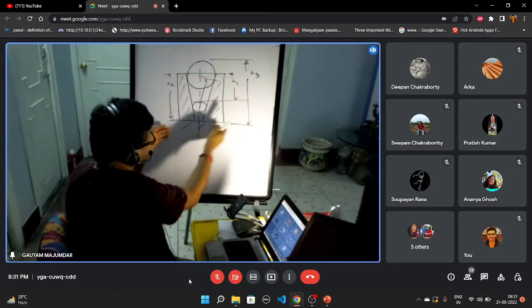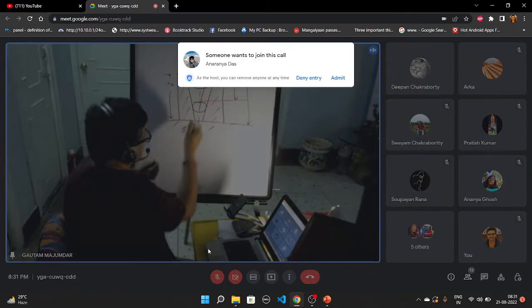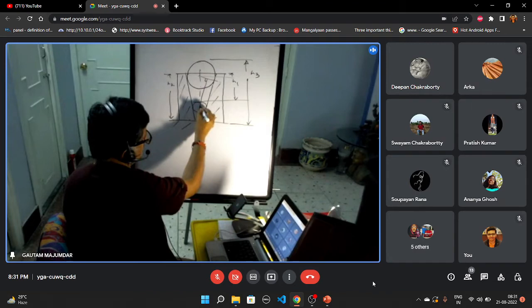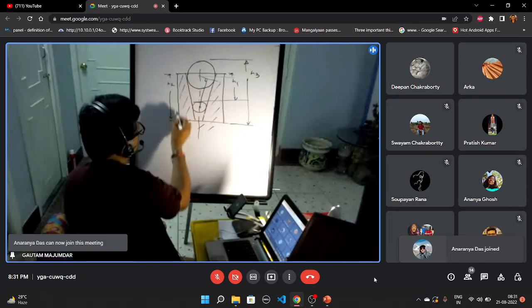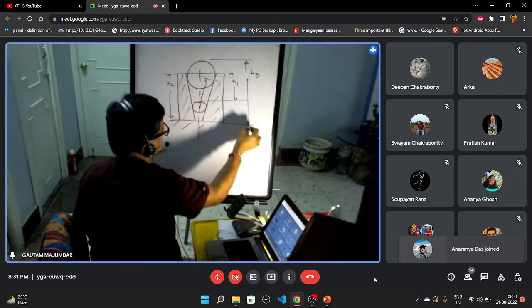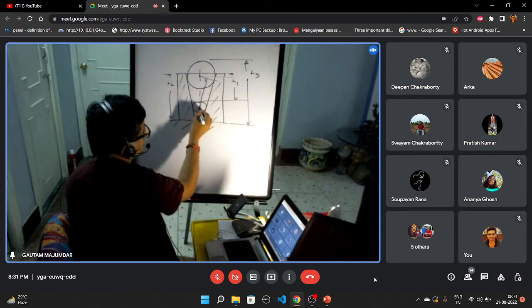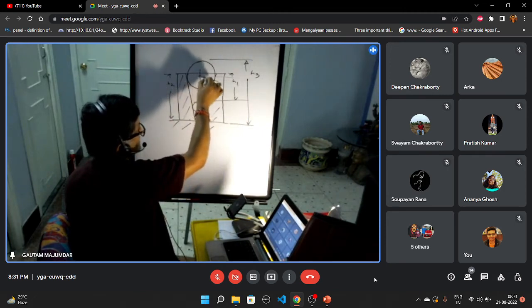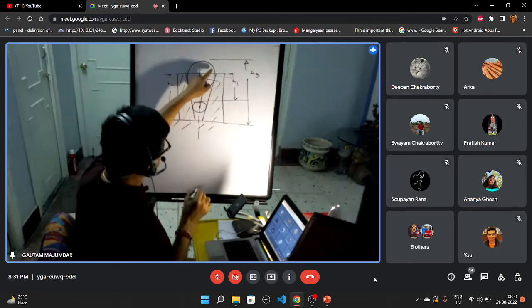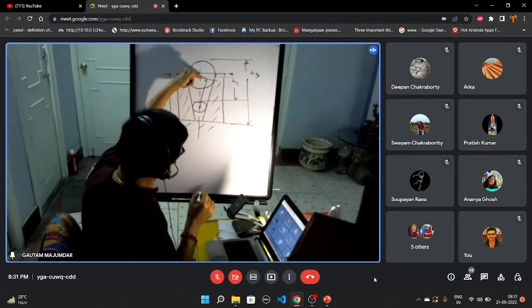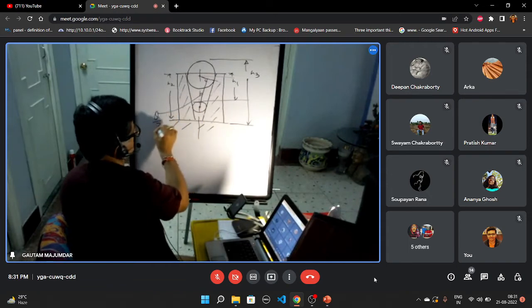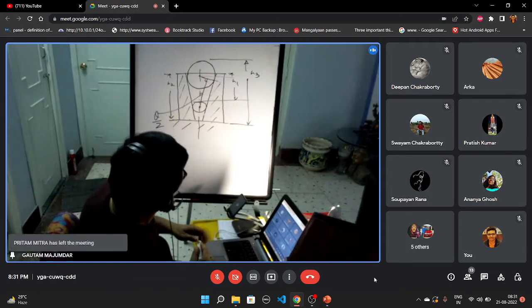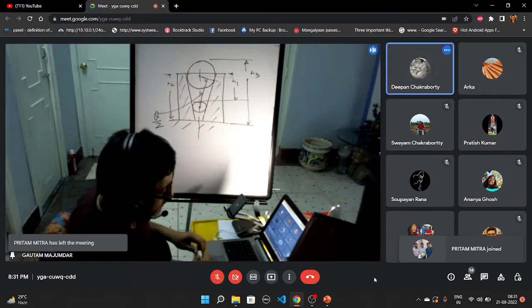So here, this is a job that you have on the surface plate. There is a ball in there, with a small depth surface. Each one is measured with the depth micrometer. H2 is the height of the job using the vernier height gauge, and H3 is using the vernier height gauge. Now what I'm telling is, if you draw this line which is touching the job, this line indicates the point where the ball has touched the surface of the gauge. And this line is perpendicular. This will be your theta by 2 line. That's what I'm telling. Yes, you have my point.